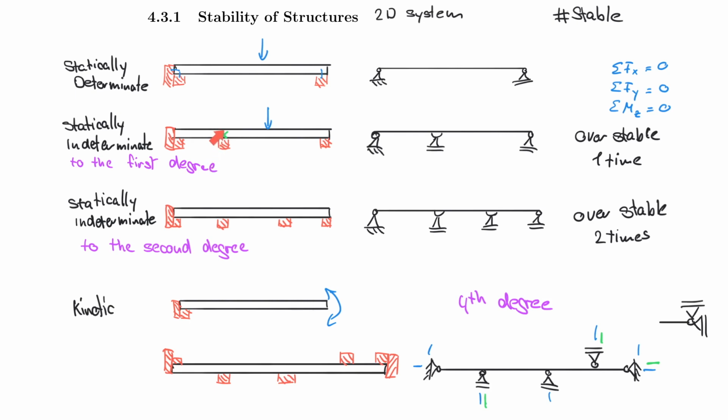But if you were able to calculate how much this deflects downwards if the support is not there, then you can use the boundary condition of the support, which says, hey, the deflection here must go back to 0 because the support does not allow this to go down, so that you can actually calculate how strong the support has to be to bring it back into the 0 position. And you can do this multiple times. This is conceptually how that would work. But what's important for us to understand is that we so far can only solve 3 support reactions because we have these 3 equilibrium equations.